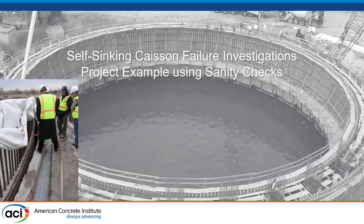So this was a self-sinking caisson. I don't know for everyone who's familiar, but they basically build these large shafts up above ground, and then they get them to sink under their own self-weight into the ground as they go. The photo here on the left is one of our principals. He just retired recently. But that's a crack that's measured in inches, not fractions of an inch. It's a delamination crack that was over 12 inches wide. The structures are pretty massive.